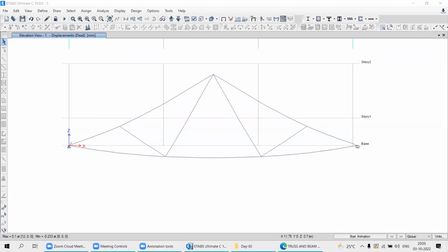Your hinge support has restraint in the translational directions, X and Y, and is free about rotation. Sorry, over the hinge support, rotation is free, and translational movement is restrained. But for the roller support, only vertical translational movement is restrained. It can move in this direction or it can rotate about the axis. So there is no restraint against the translational movement in the X direction or against rotation. So that is the proof.